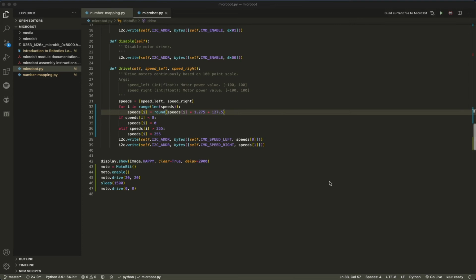And so we can fix that two ways. Either flip the polarity of the cables of the right motor. So you know how it tells you to plug in the red cable at this spot, black cable at this spot. All you can do is just flip them around and switch the colors around. Or we can do it code wise, and I think it's pretty cool.